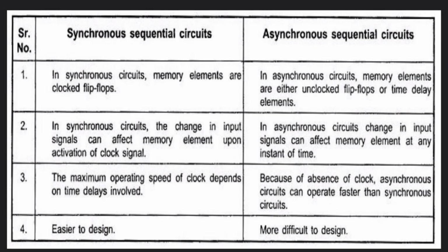Difference between asynchronous counters and synchronous counters. Synchronous: in synchronous circuits, memory elements are clocked flip-flops. In synchronous circuits, the change in input signal can affect the memory element upon activation of clock signals. The maximum operating speed of the clock depends on the time delays involved. Easier to design.